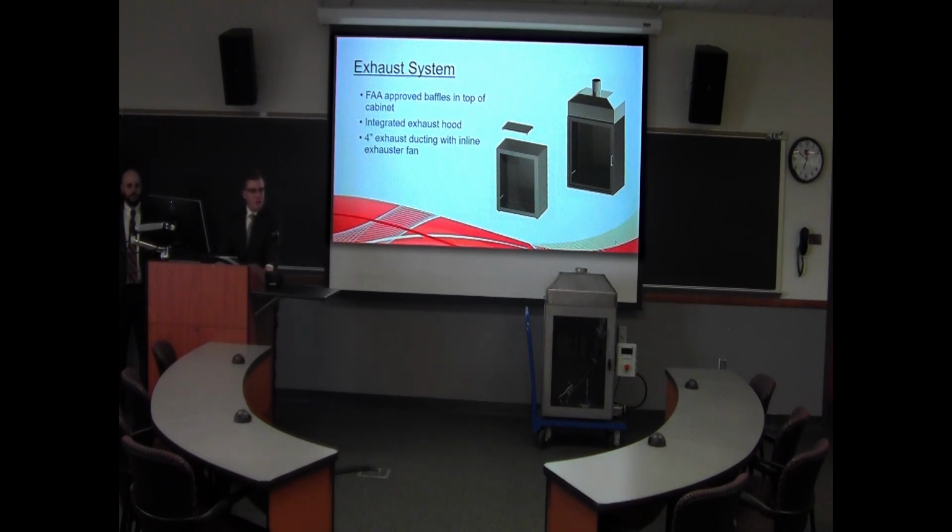We also built an exhaust system for the cabinet. Now the exhaust system is an integrated hood, so if need be, it can be removed. What you would see if it is removed is the picture on the left with just the baffle. That can work, but if more hazardous materials are being burned, they might want to put on the exhaust hood so they can evacuate the hazardous smoke. And that is evacuated by a 4-inch exhaust ducting inline with an exhauster fan.